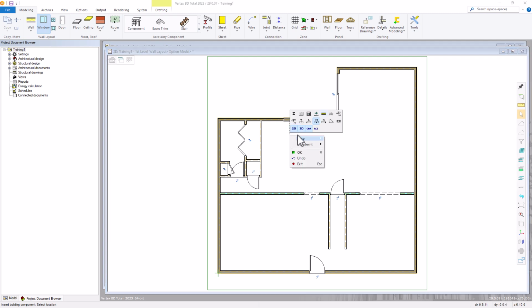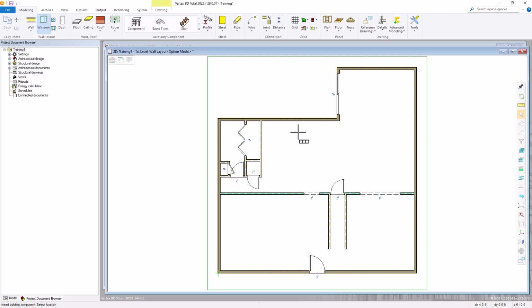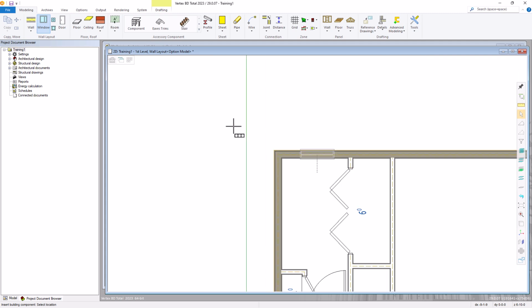Now if I right click, you'll see that we have similar tools as the door auxiliary openings menu. Same Z, again, parameters, remove the siding over the opening. Everything is the same, other than I think the flip and mirror really won't be used as much when it comes to windows. So let's go ahead and leave it at midpoint or center. Let's add this window to the bathroom. So we're going to find the midpoint of this wall here. Get the yellow triangle right there.